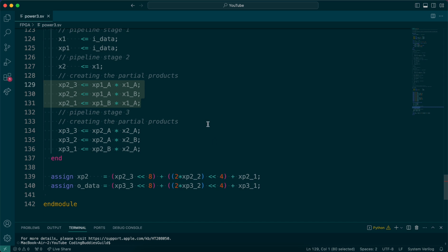This is how you can use this technique, which I call the parallel structures. Sometimes you cannot, and if data is dependent, there is nothing you can do about it. But in most cases, honestly, if your design didn't meet the timing, this is a good technique to use. You just break it down into smaller pieces and do them in parallel. I'm thinking about if there was anything else that I would like to add here, but honestly, I cannot think of anything.